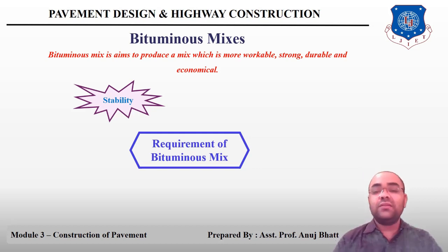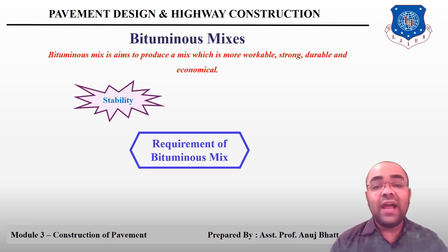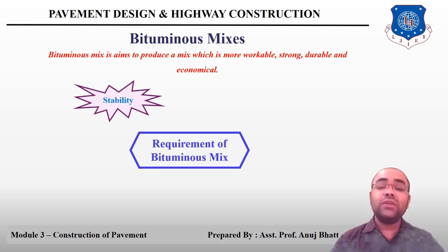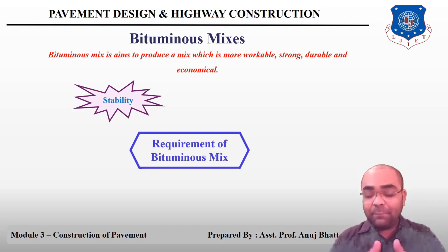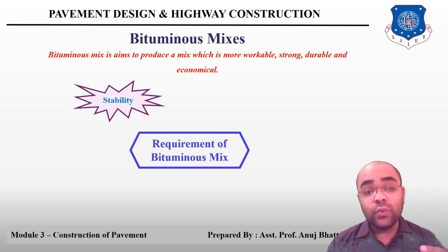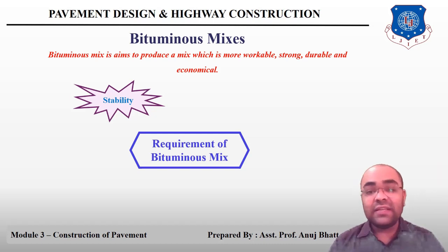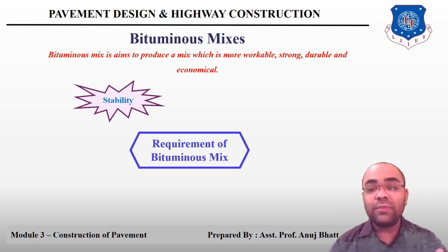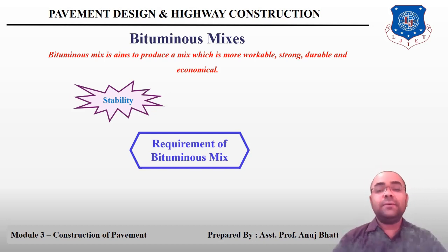Sufficient binder must be available to coat all the particles at the same time. However, the stability decreases when the binder content is high, and when the particles are kept apart. So if you are applying more binder content, that will also decrease the stability, and also if you keep the aggregates apart from each other, in that situation it also decreases the stability.